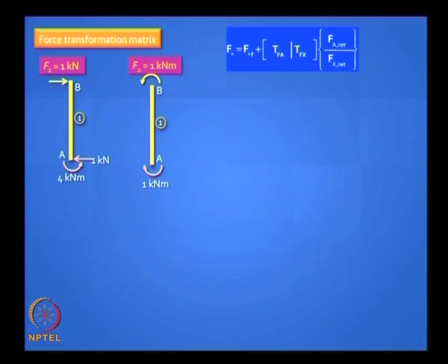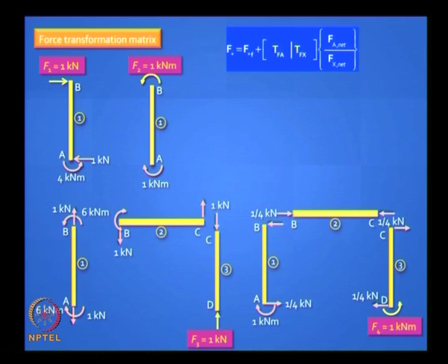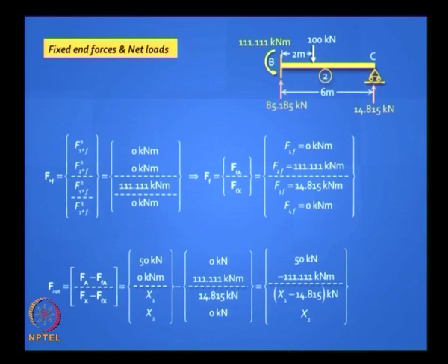Force transformation matrix, much smaller, much easier, F1 equal to 1, F2 equal to 1, same results, these two do not change, F3 equal to 1, F4 equal to 1. Same, only we have renumbered them. F6 became F3, F7 became F4. Your size of your TFA matrix is shrunk to a nice compact size, right? You can interpret the results very easily.